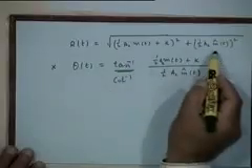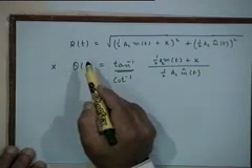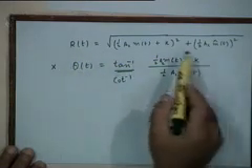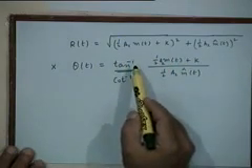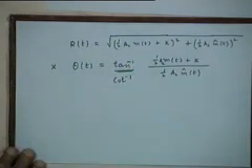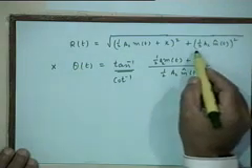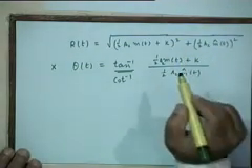Okay, so now let's look at this expression for the envelope. I would like the envelope to follow the message signal. Can I make some assumptions which will make it so? Under what conditions will R(t) approximately follow m(t)? When K is very large. Correct. So that's precisely what we'll do. We'll choose our local carrier to be added with sufficiently large amplitude, so that this term dominates over the second term,